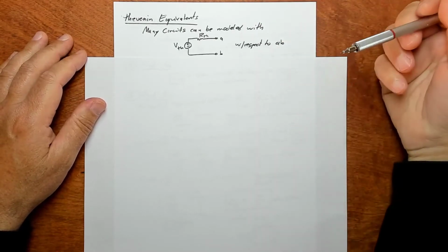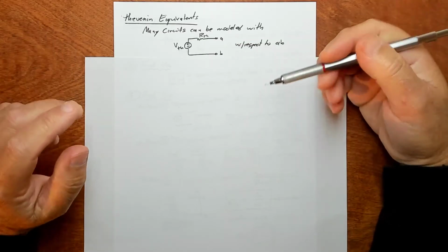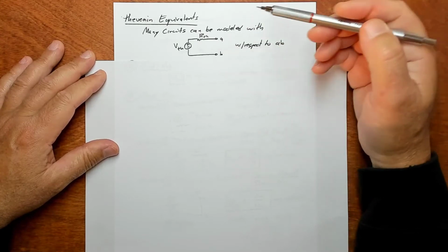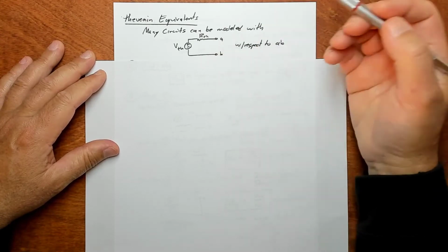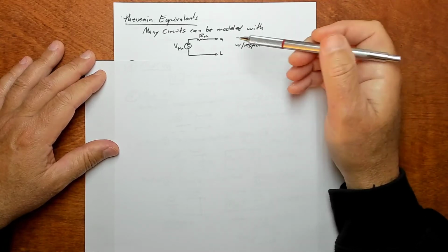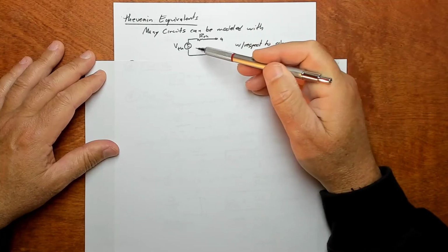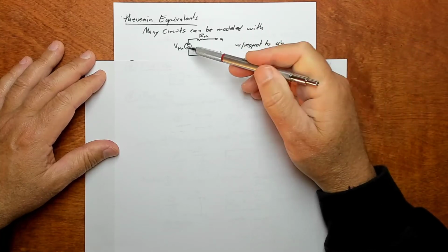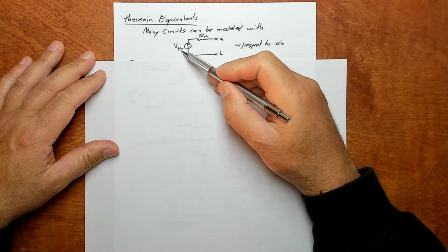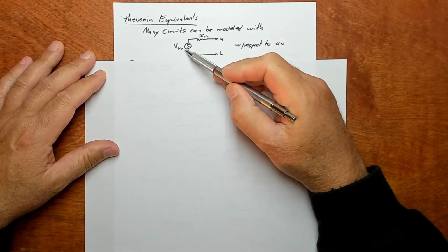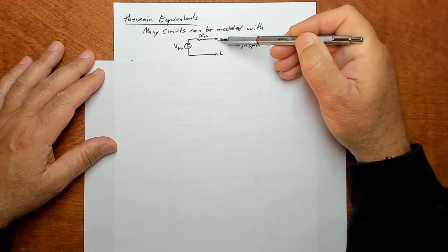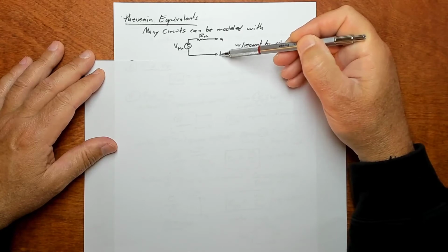Now we're going to go through this lots of times, but right now, here it is, just throwing it all out there. Turns out, which you saw in chapter 2, I think, that most circuits can be modeled with this simple circuit here, consisting of a voltage source and a resistor. We call the voltage source V sub Thevenin, or TH for Thevenin, and R sub Thevenin. Most circuits can be modeled with this, and that's what we were doing in chapter 2 when we had tables of voltage and current measurements.